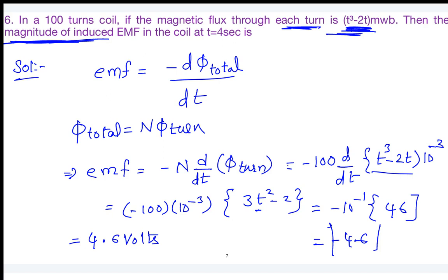Okay. Now, this is what the problems I actually planned for the magnetic circuits. If I summarize it here, all the concepts of the magnetic circuits and Faraday's law together, it's all about 4 concepts as I mentioned earlier: the MMF, reluctance, the flux per each turn, and the flux linkage and the inductance.